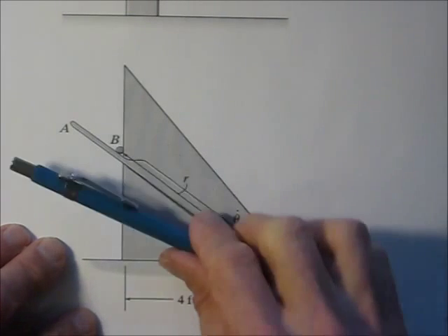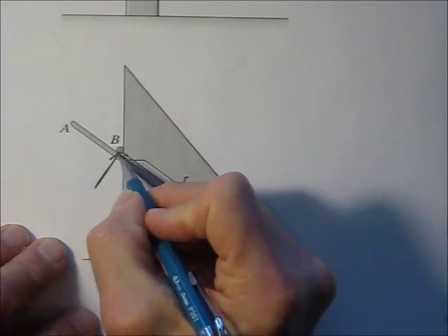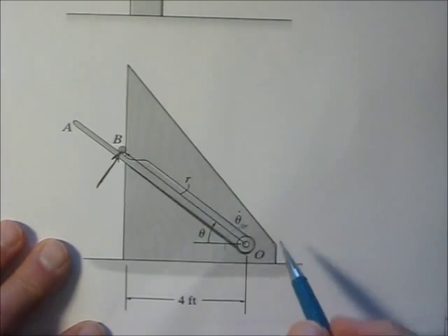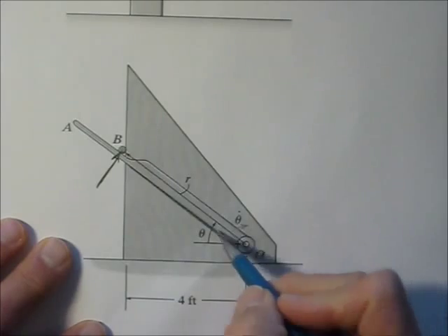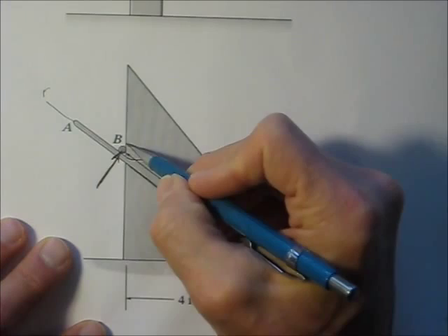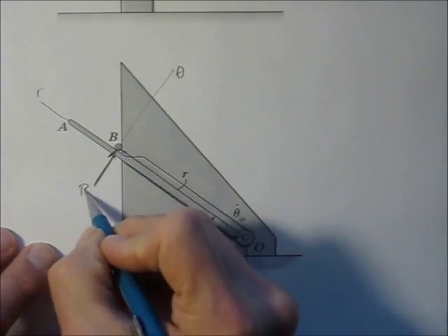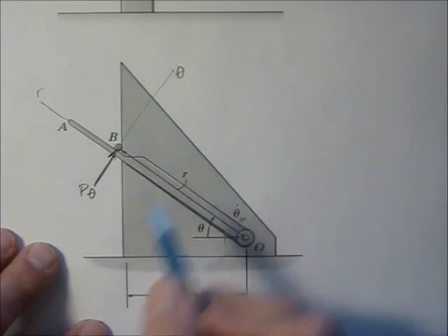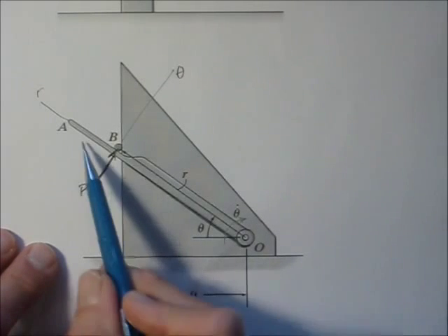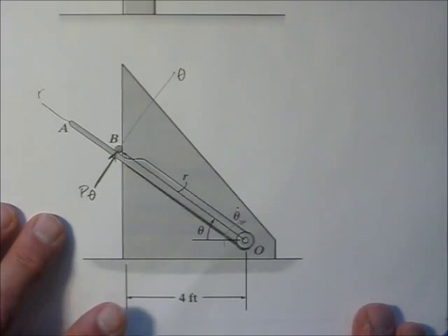But just recognize here, as this thing moves up here, there will be a force pushing the bar in this direction caused by the bar right here. And if this is the r direction pointing out like that, and theta is going this direction, this will be the theta direction going up like that. So this would probably be considered P theta. In other words, what is pushing the particle by the bar itself. But recognize also the path has some forces on that little particle too.